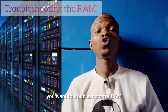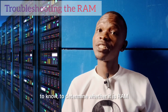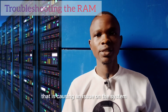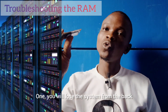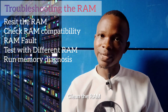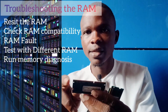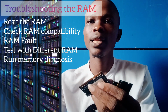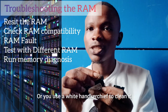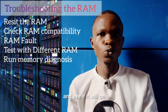Now for RAM, if you want to troubleshoot, the number one thing is to determine whether it is RAM or not that is causing an issue on a system. One, you will open the system from the back. Remove the RAM, clean the RAM. Look at this pin here. You will clean this pin. You can use something like this to clean it, or you use a white handkerchief, and then you slot it back into your system and see if it will come on.